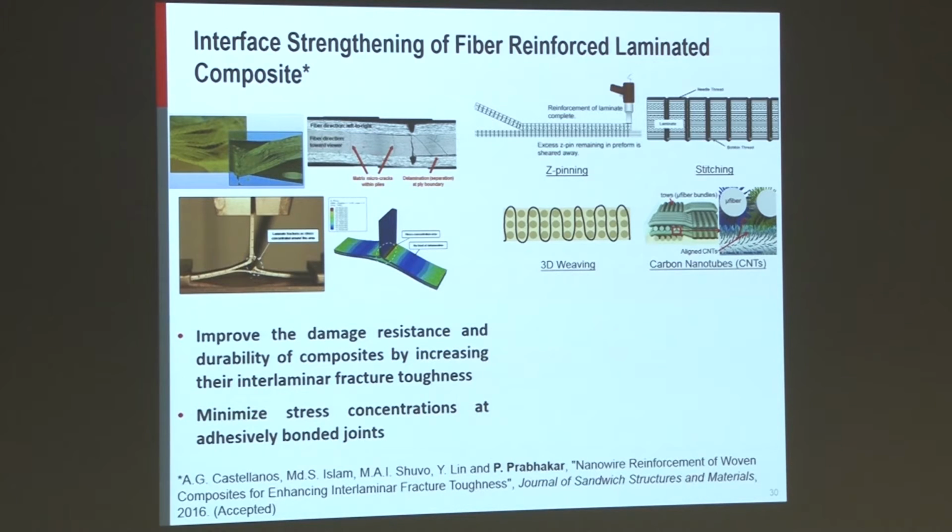These reinforcements in the thickness direction pass through all the layers of our material. They did increase the through thickness response significantly, but they also reduced the in-plane response drastically because they caused failure of fibers, change in volume fraction during weaving, and crimping of fibers. That caused extra damage in the in-plane behavior, so these were not very successful in improving the overall behavior of the structure.